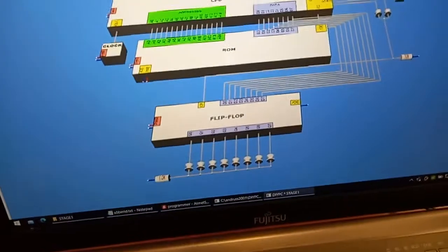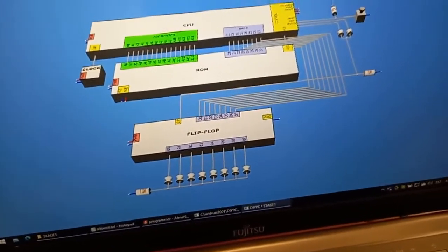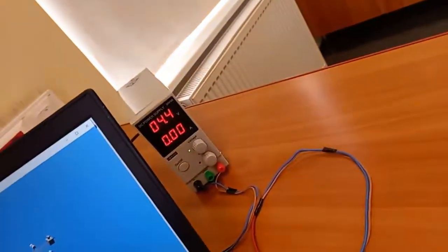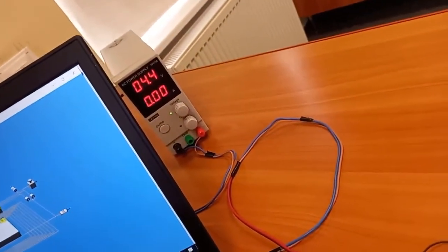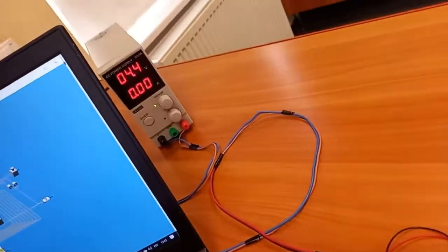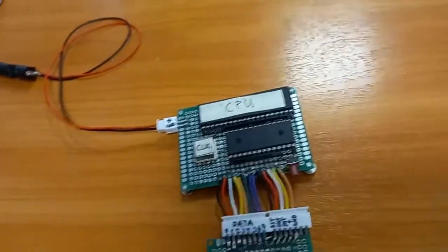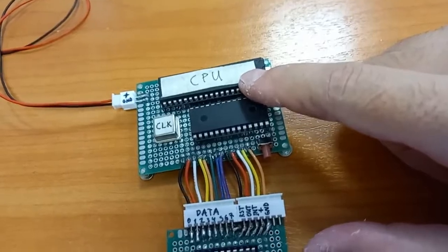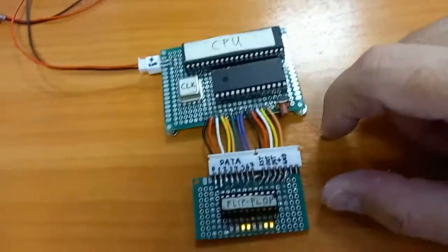You can build yourself something like this, you just need some soldering skills, and as a power source you can use a charger from your phone. For example, you have 5 volts there, you can direct them here. This chip works from 3.7 volts or so to 5.5 volts. They are pretty tolerant.